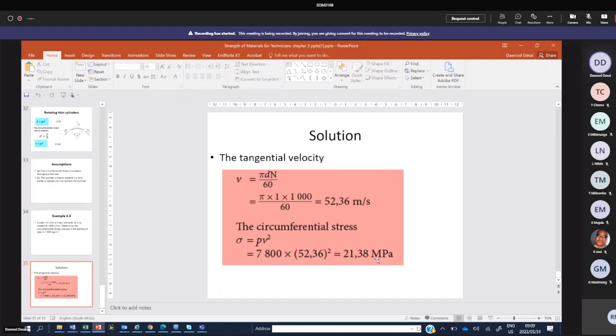Okay, so do you need to be scared? No. All you need to do is a force equilibrium, like we did yesterday. The load W must be equal to the summation of loads that are resisting it. Internal force must be equal to external force. So the internal pressure must be equal to the external pressure. What is the external force? The force in the bolts. Sometimes they give you 5 bolts, so you have 5 areas. I hope you're listening very carefully to what I'm telling you. It's nothing difficult.